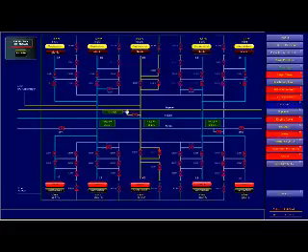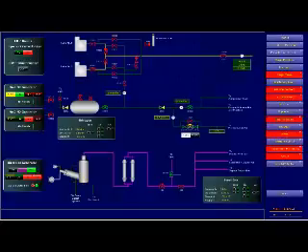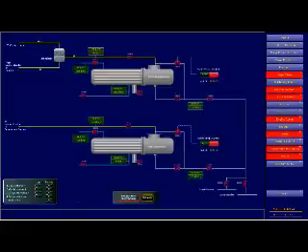Okay, then we have got our engine room alarm, where we have got our nitrogen generator running. So wherever the nitrogen will be required, either to compressor seals or purging headers, or pressurization of interbarrier space, this will be going there. The vaporizer at the moment we are not using, they are in a secured condition.